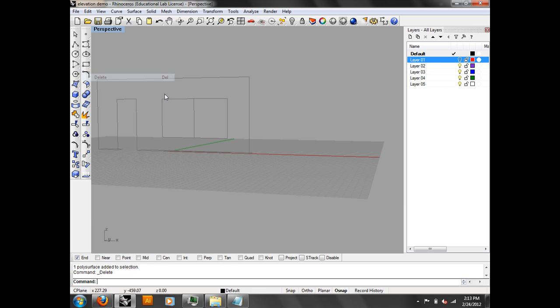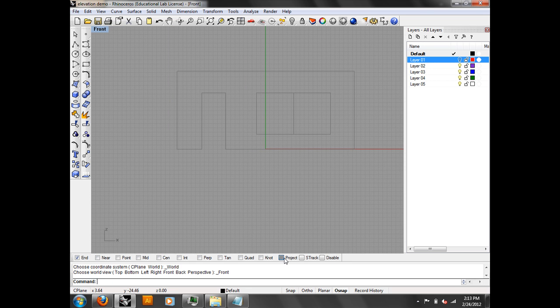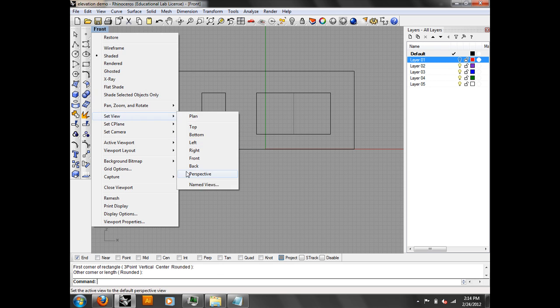So what I do is go to that elevation view, turn off the plans, and turn on project so that I'm flat. And then I would actually retrace the geometry. The reason for this is that you actually know what you're getting. Everything that you do, you know that it's a joined shape. You only trace the forms that you want. So if you are getting a push and pull, you're actually tracing the areas that get pushed and pulled. Then you make that operation, and knock out anything that you have for windows. This is very simplified, but this may be all the level of detail you need.